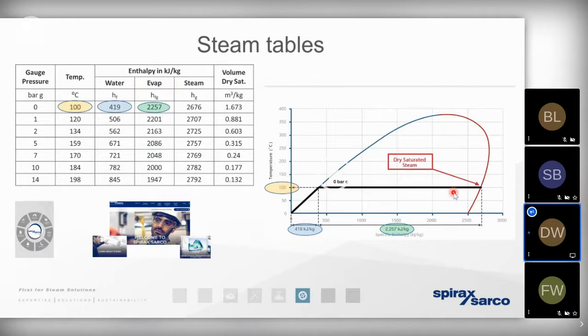We now no longer have water in the boiler. We've got 100% dry saturated steam. And that tells us that once we've added the full enthalpy of evaporation to the boiling water, we can see what the total heat content is here. So dry saturated steam, critically important. The term saturated means the steam's saturated with energy. It's physically incapable of holding on to any more energy than is demonstrated in this column here. Dry tells us there's no moisture entrained within the steam.